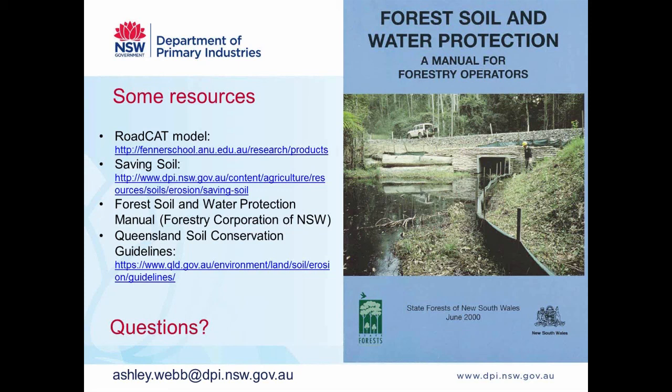I just had, I guess, a point of clarification. You talked about infall or outfall roads and mentioned that outfall roads were the better way of shedding water from the road, but in certain circumstances they weren't appropriate. And I just wanted to clarify that often on steep slopes is where they're not appropriate because it's dangerous for them to be built and to be transported on. Is that correct? Exactly, Abby. Yeah, that's what I was getting at.